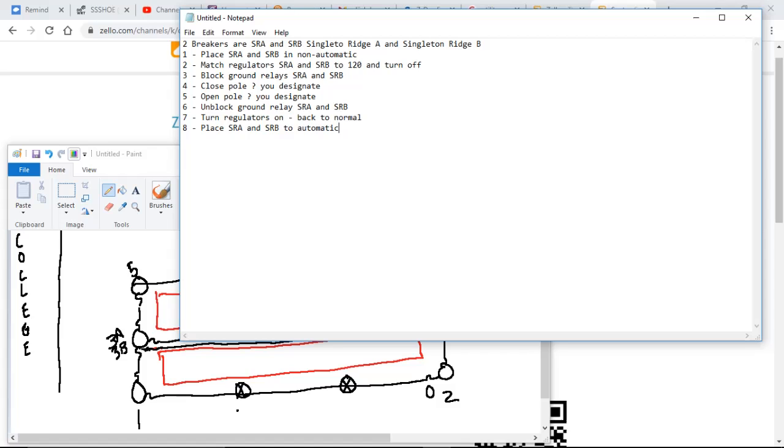I'd just like to make a statement about the switching instructions: from company to company, procedures will vary. I'll give you Duke's procedures. Whenever we get our switching instructions, just like what you have here, it'll be written out. Because of SCADA, anything that's done in the substation is usually done by dispatchers, and they will let you know that those steps are complete, and then you will repeat back just like what we did. Repeat back to them that you understand that those steps are complete on his side, that he's already taken care of that. Excellent point right there.